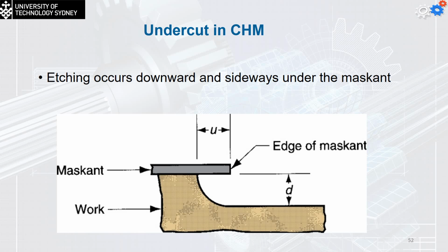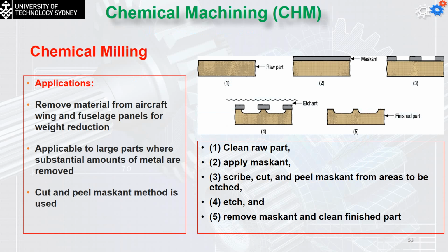When a mold was designed and the material put inside shrinks later, we oversize the mold. In this case, I will simply undersize the shape I would like to have on the maskant. So the material will make it bigger, which is going to be my desirable size. So undersize the mask size, and this will do the work.